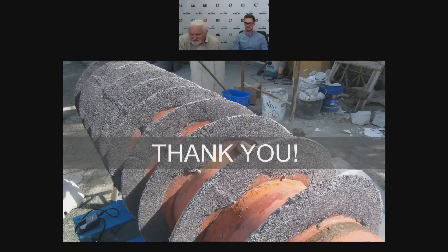Again, dependent on temperature. As the ambient temperature or the operational temperature increases, you get closer and closer to the heat distortion temperature of the material. That is the temperature at which the material begins to become more plastic, and therefore its physical properties begin to fall. So provided you stay well under, within about 10 degrees below the HDT of the product, then it should perform very well.